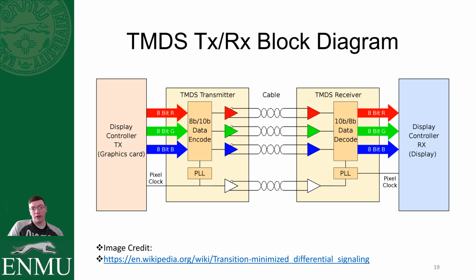The triangles on the left are a buffer. One is just directly connected. One is an inverted buffer. And so those signal levels are always equal and opposite to each other. And on the other end, the triangles on the right, you just have op amps, which are canceling out that noise and returning those differential pairs back into a single pair. And the fourth one, the white triangles at the bottom, are the same thing. It just happens to be the clock channel.